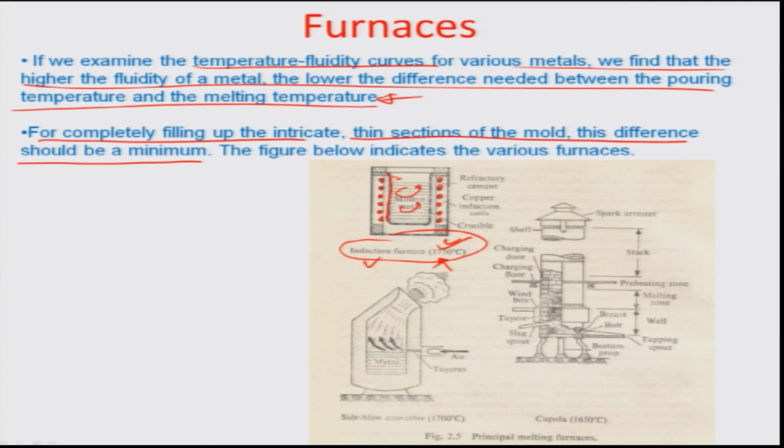So, the crucible can sustain the high temperature conditions where the metal gets into liquid state. There is a refractory cement which holds this crucible in place, so that the cement is able to expand and hold the strength at a higher temperature. So, whatever outflow of heat happens from the molten metal to the furnace can be protected on one hand, and on the other, the strength can be kept intact, so that this cup does not vary in size or shape, or does not go down. So, that is how the induction furnace is.